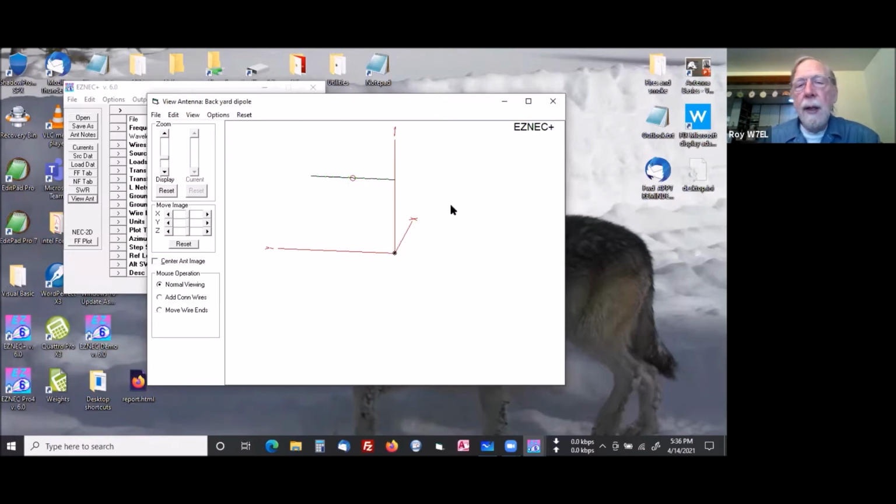I haven't accounted for any radiating feed line, for example, which can be really significant. You can model that with EZNEC in cases where it is significant. Like if you tied a coax cable to this antenna and put it down, then with no balun up there or no common mode choke, the coax would become part of the antenna and would radiate, and we can model that with EZNEC. And if you have that situation, you would have to have that as part of the model, or the results you get from EZNEC wouldn't represent the real antenna.